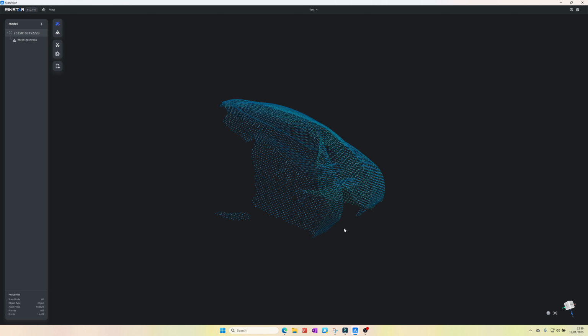Click Generate Mesh, and with a computer having over 32 GB of RAM, you can achieve a resolution limit of 0.1 mm. Initially, I'll disable mesh smoothing for comparison purposes. Though 0.1 mm may be excessive, I'll start with the recommended value of 0.14 mm. Previewing the process will take some time depending on the resolution and model size.